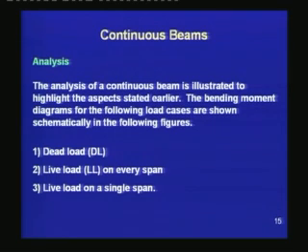The analysis of a continuous beam is illustrated to highlight the aspects stated earlier. The bending moment diagrams for the following load cases are shown schematically in the following figures. First, we shall observe the bending moment due to dead load. Next, we shall observe the bending moment due to live load on every span. And third, we shall observe the bending moment due to live load on a single span.